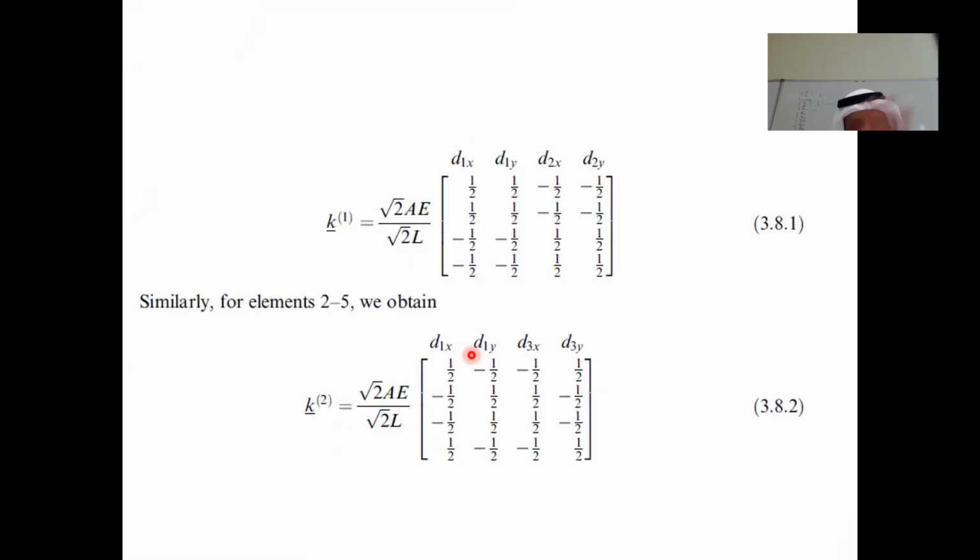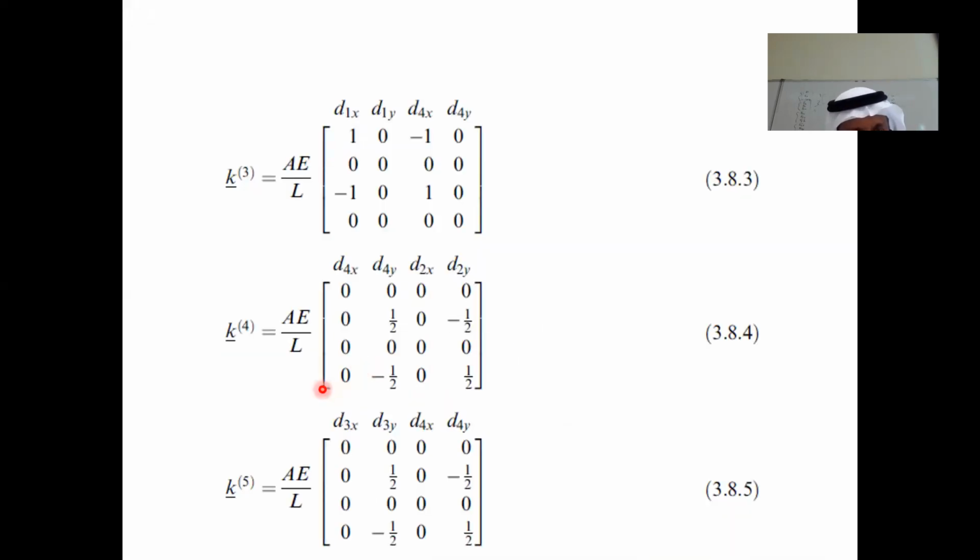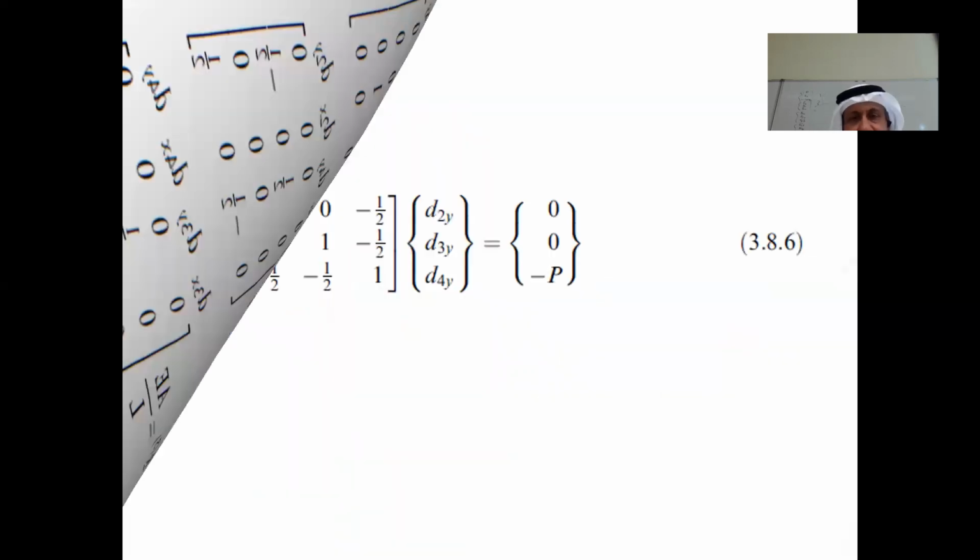Stiffness for K1, it's okay. What are the 2 members? 4 and 5. There is half here. Did you see the half? If you don't cut it, it just looks like you just divide by 2. You take EA divided by L. You just divide it by 2 or multiply it by 0.5 because you cut it. Because EA divided by L is K, so it's K over 2. And similarly for 5, it's half, half, half. That's it. You can solve the problem now.